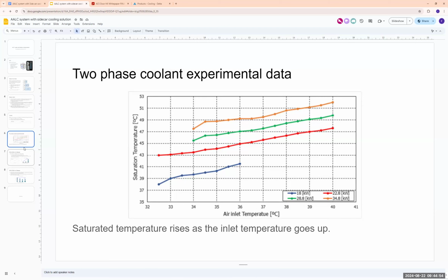Because in a regular system, if the supply temperature goes up, you have a certain approach temperature, which means your coolant temperature goes up, so in turn you have certain limitations. But in this, your supply temperature, your coolant temperature doesn't change much, I guess. But your coolant capacity might change. So I need to find out what that relationship is, and then I'll write it down.